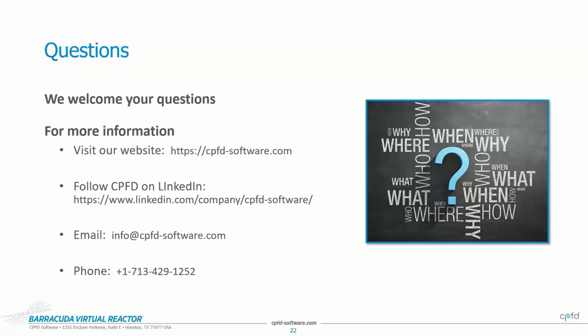Thank you. I think that's a really good answer to that. I know there's a lot of good correlations out there. I'm mostly familiar with the PSRI ones on recommended minimum pressure drop across the distributor relative to bed DP, but it's a tricky thing, because if you want as uniform a flow as possible through the distributor, you increase your pressure drop, which typically involves raising nozzle velocities. But that could affect your attrition of the particles. So there's a sweet spot there, and I'm excited that our users now have a tool to explore that further.